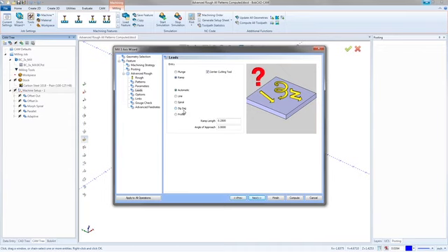You will at some point probably have to come in here, and if it picks a spiral, you'll look at it and go, nah, I'd rather use a line, and you'll come in and pick a line. But by doing automatic, you might get a line entry on, say, the top boss, the one that's standing, and then a spiral for the one that brings you down into the middle of that pocket. And it'll pick that automatically depending on what settings you put in.